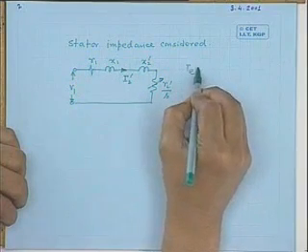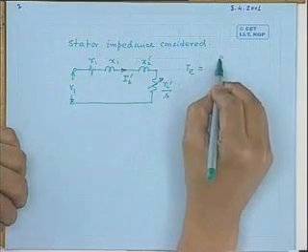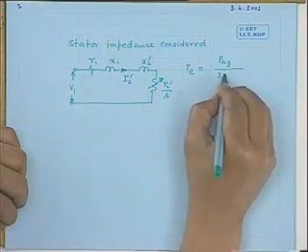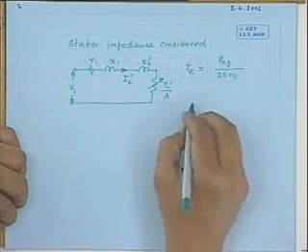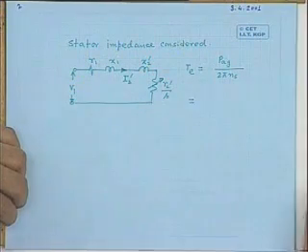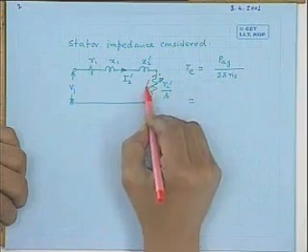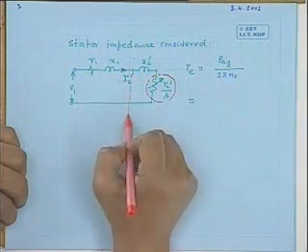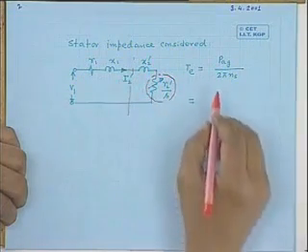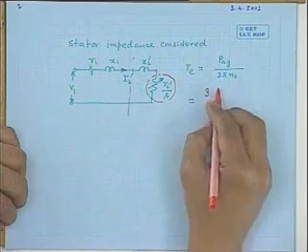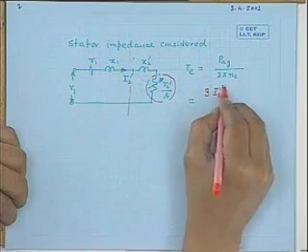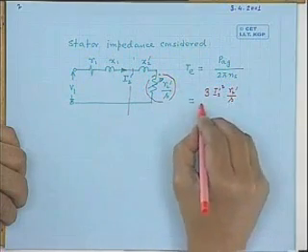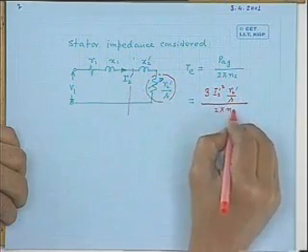The torque developed, if you want to calculate, should be equal to the air gap power divided by the synchronous speed, 2 pi ns. Now what is air gap power? Air gap power is the power involved in this resistance. This is the power which crosses the air gap and comes to the rotor at this point, real power. So this will be 3 I2 dashed squared into R2 dashed by S, and the whole divided by 2 pi ns.